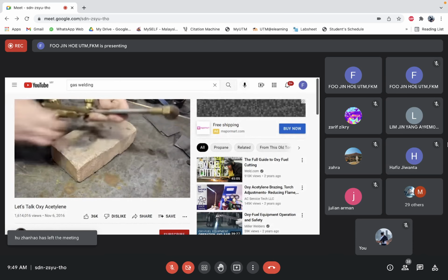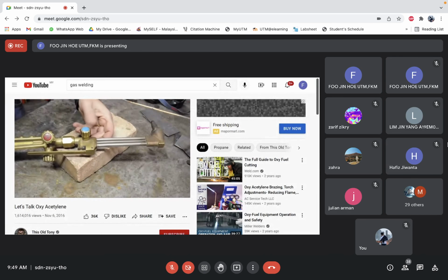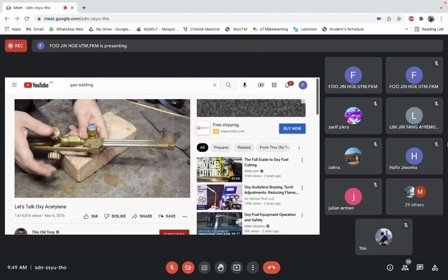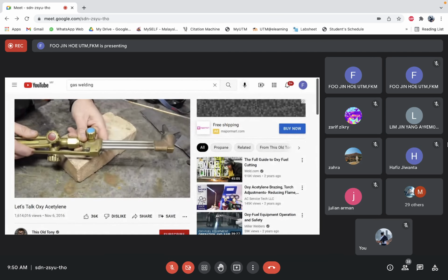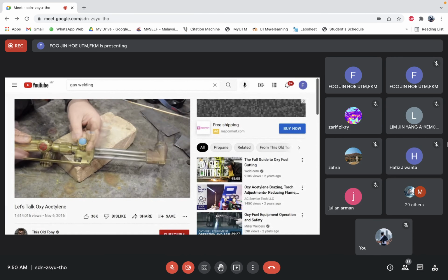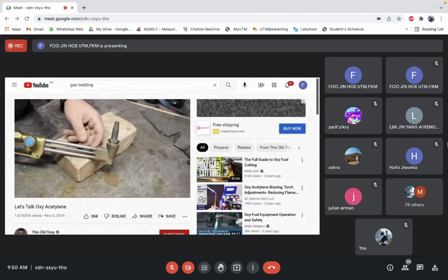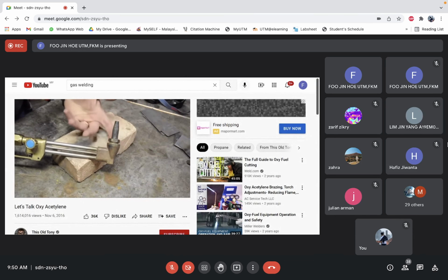So I just put the cutting head on. It might look a little complicated, but there's really not too much to it. Anyway, same adjustments as before, acetylene and oxygen to get us to a neutral flame. And then there's an additional oxygen valve. Now, cutting requires a lot more oxygen than welding did. Even a modest sized tip like this, I don't remember the number exactly, but this will cut some ridiculous thickness of steel.